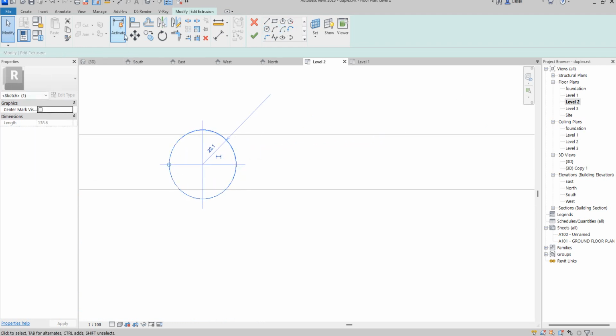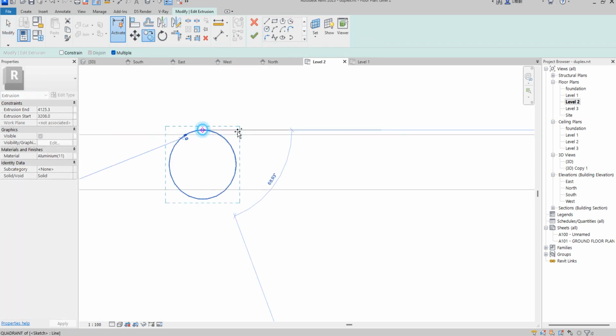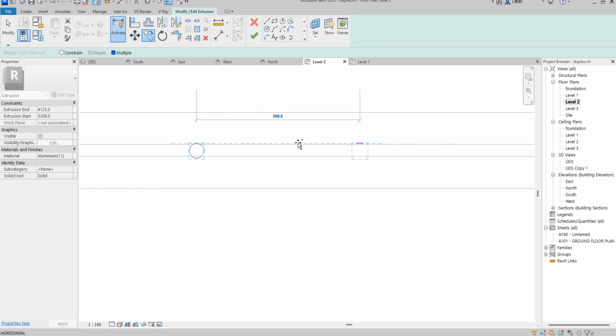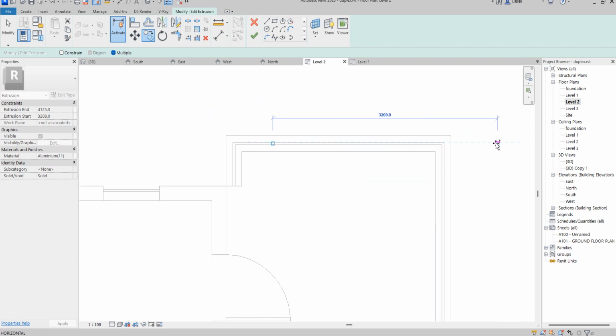So what you do now, you start copying from here, then use specific distance to the very end. So take it above. So now you start, use your keyboard, start typing 1200 spacing, 1200 spacing, 1200 spacing. Okay, it's more than what I need now.